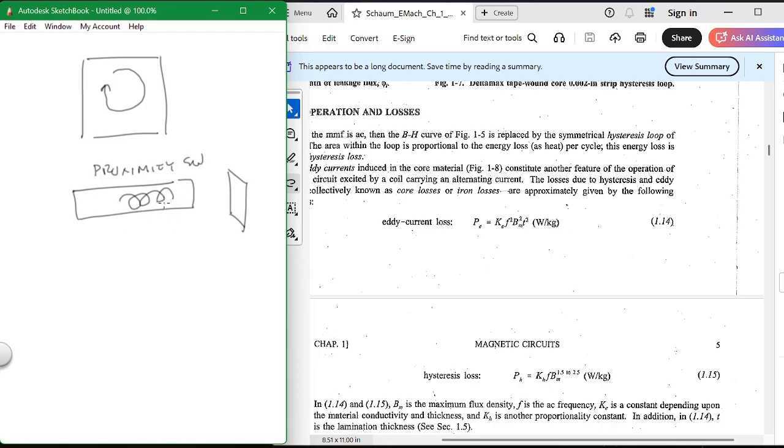And that secondary coil, what does it tell you? If there's current, there's metal in front of it. That's a prox switch. That's how a prox switch works. So eddy currents aren't always bad. They can be bad, but they don't have to be bad.